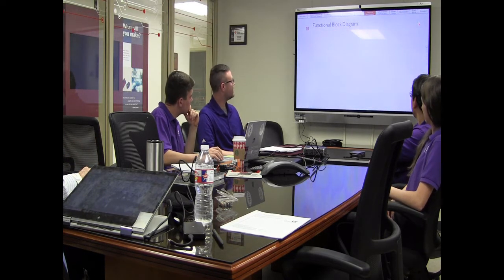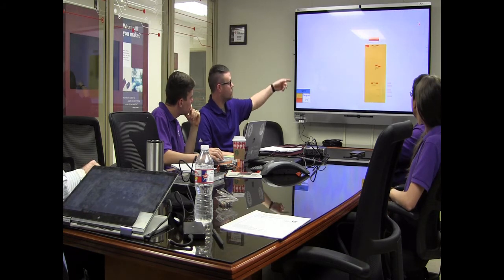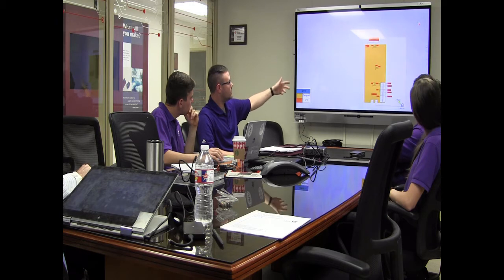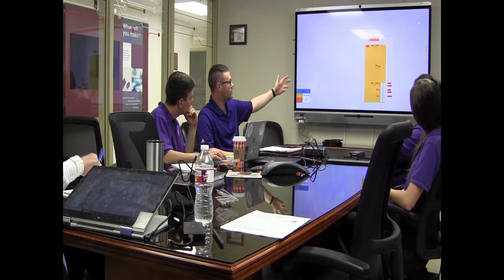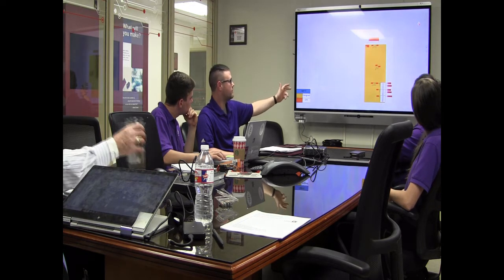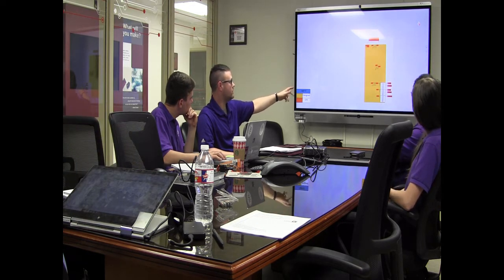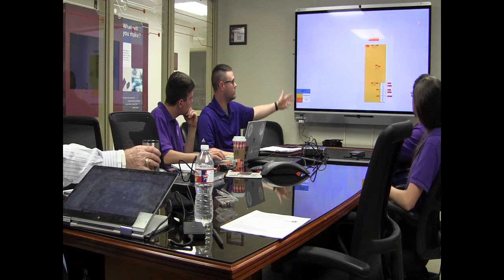So, and then functional block diagram. Is everything we've seen before. Power comes in through the wall. We've got 3 different voltage regulators. The top one knocks it down to 5 volts. Next one also takes 12 volts in, knocks it down to 5 volts, and then routes out to the 3rd voltage regulator that takes that 5 volts in and knocks out 3.3 volts for our CC3200 and our sensor pack.